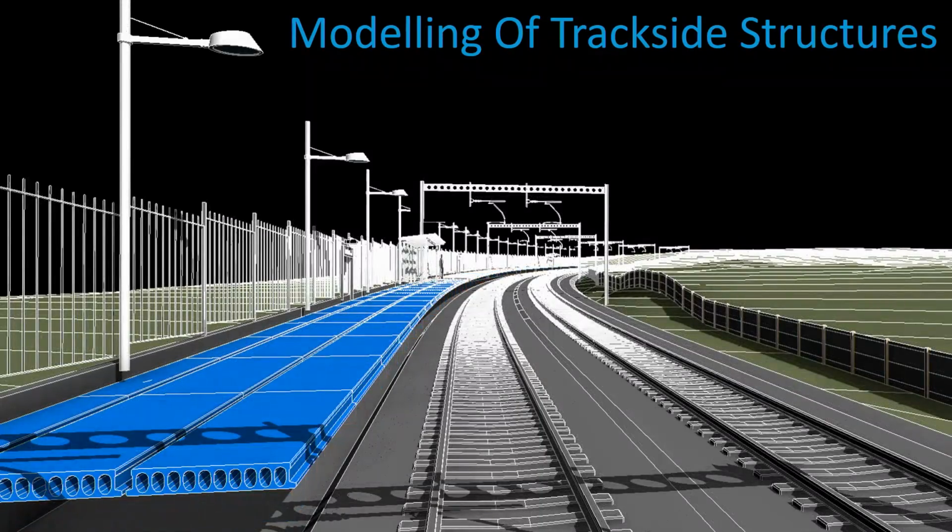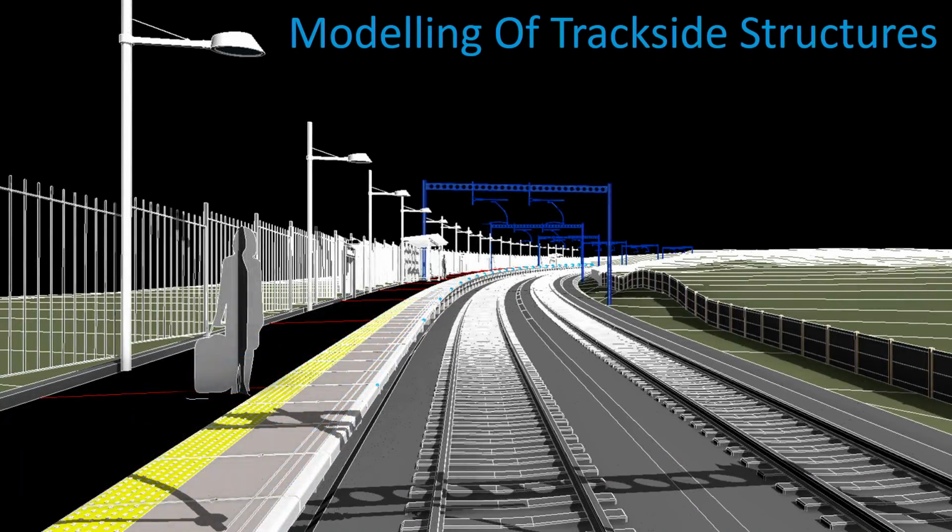So the next step is to place the precast hollow core planks. These are variable. You can see we've got two different widths here. That really is dependent on how wide we want the platform, but this is modular, so of course it can accommodate all sorts of different widths. Again, they're beam members. And finally, what we're doing is we're placing the precast coping stones along the edge of the platform here, and also creating a structural topping over the top of those precast planks, which would be an enormous task to try and do inside Revit alone.